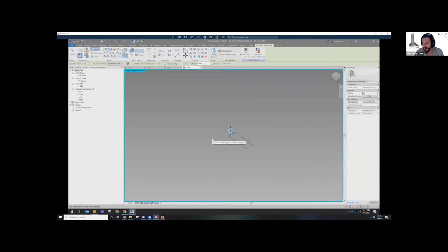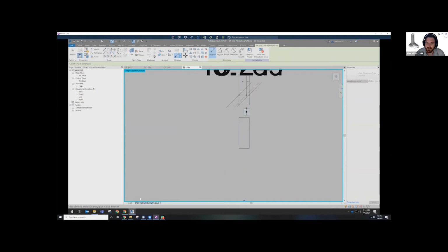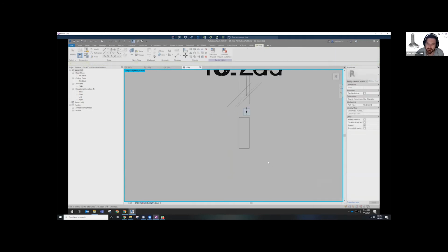If you're just doing very quick studies, you can do it this way, where you're just drawing things. In adaptive panel land, dimensions and constraints generally aren't the best way to go. So for example, if I create a dimension from this line to here, something like that, and I change my scale very quickly, if you start to equals it, it's going to start breaking. This introduces us to one of the first examples within adaptive panels, which is the idea of offsetting points.